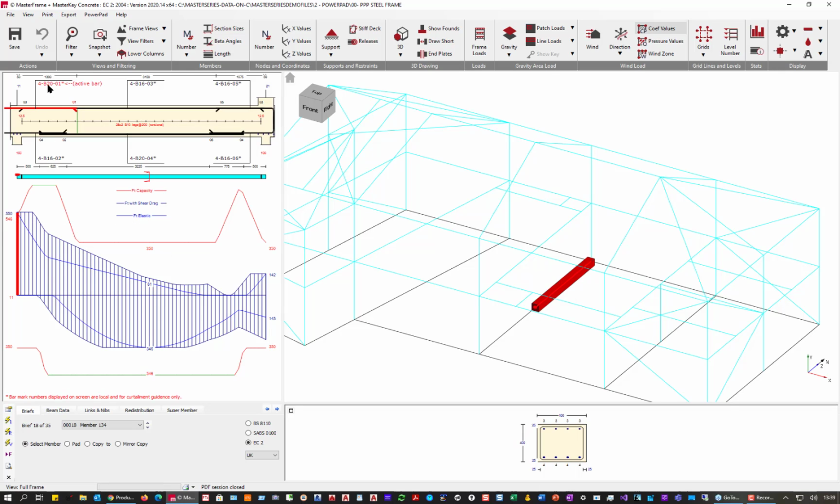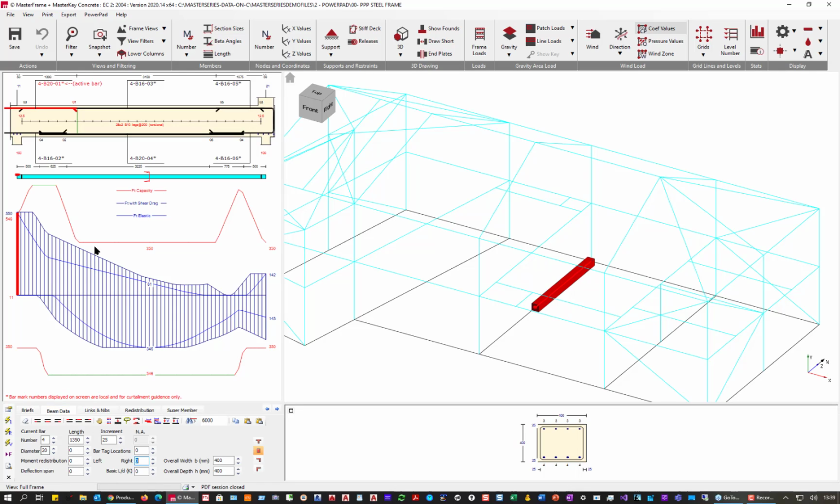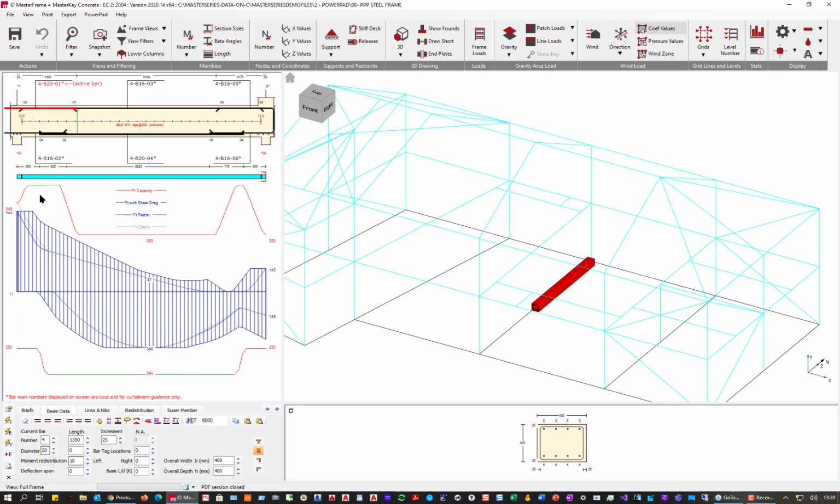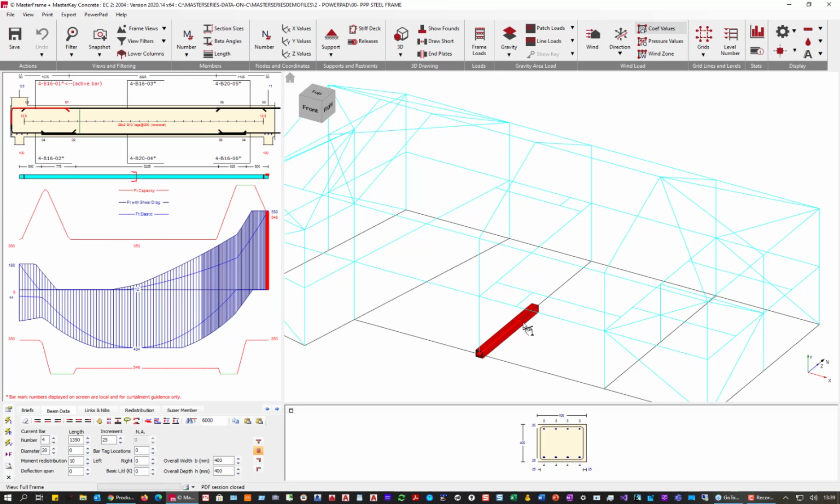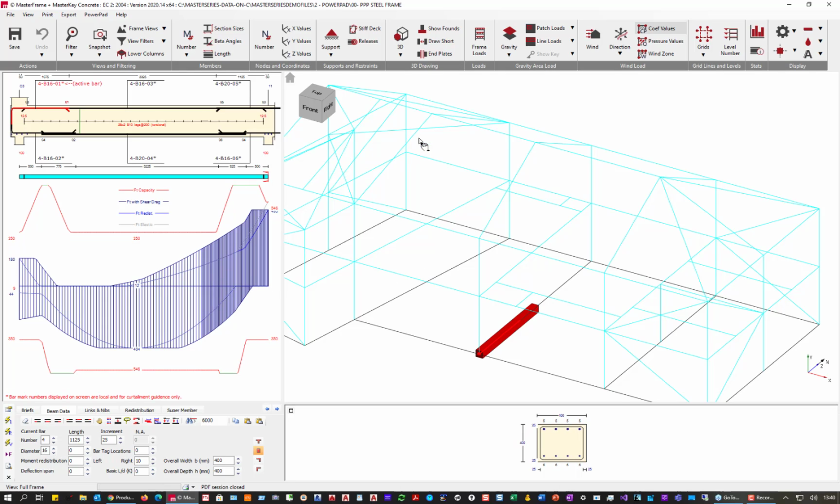It's failing. We could go up to 25s, or we could go for 5 bars, but an alternative to that is very simple: to come along and say, right, left hand side, let us pop ourselves in a 10% redistribution, and likewise on the other side, just to make it right, pardon the pun, a 10% redistribution.